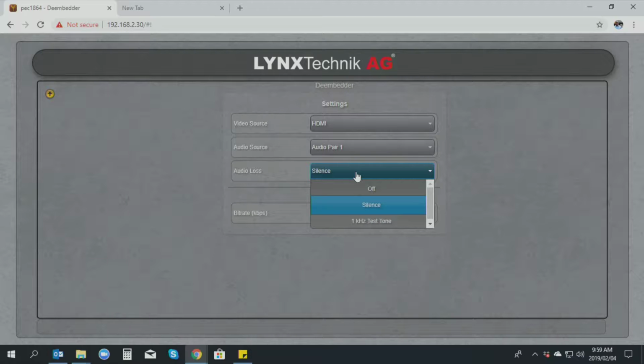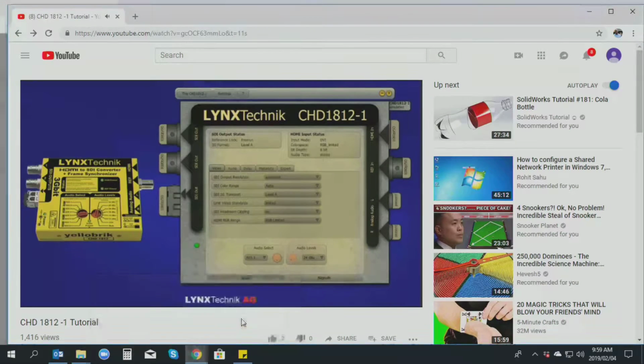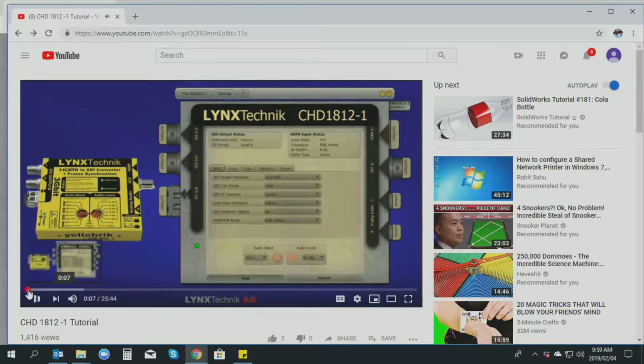It's a very sophisticated frame synchronizer, and it's capable of cross-locking. What that means is it's even possible for you to put a 50 Hz input on the HDMI and give a 59.94 reference, and it will actually give you a 59.94 output. That's the way the module works, is that you're a slave to the reference input.